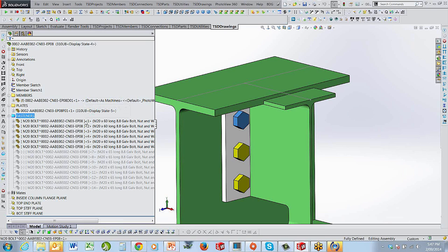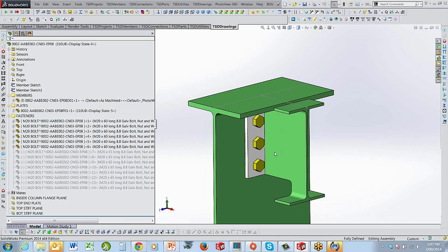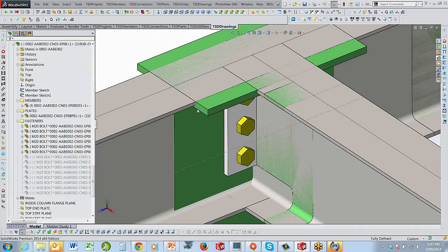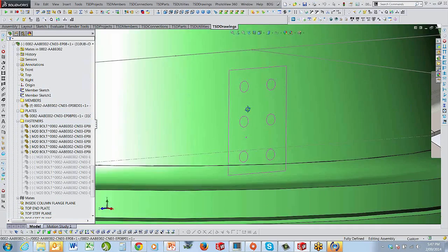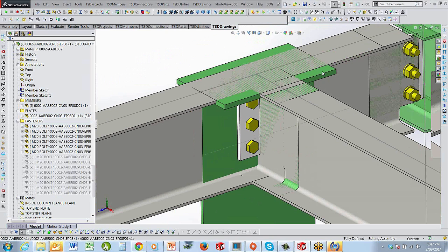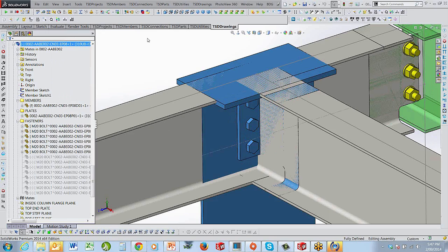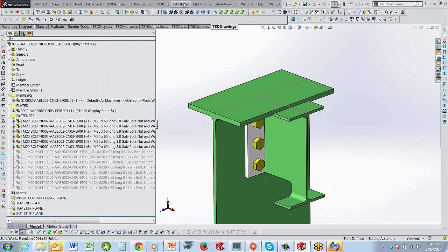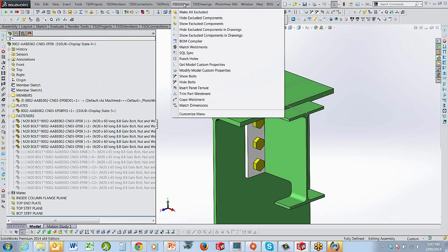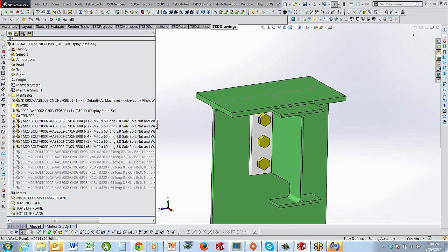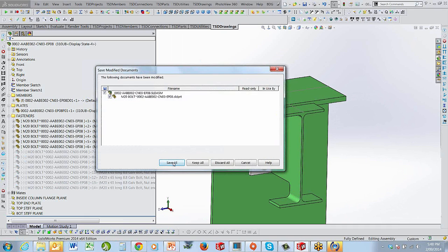Now you can show them or you can hide them. It's up to you. Either way, you can use the hide or show fasteners, which we've got as a utility. However you want to count them, and to count them, they can be hidden, which is not a big deal. We go into that member, as I showed you before, we can actually show them and hide them. So under the utilities, if we go hide bolts, they're gone. Utilities, show bolts, they're back. Just as simple as that. So we've built that functionality in there for our customers.